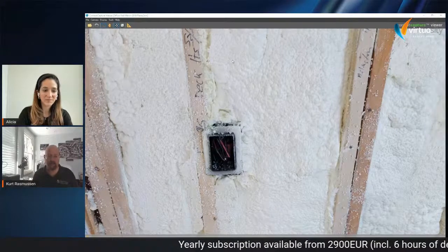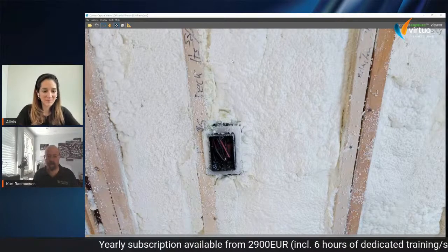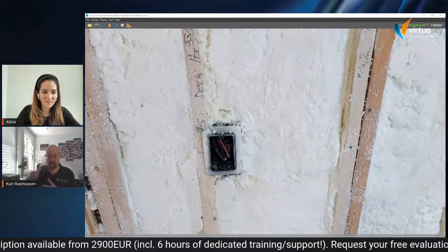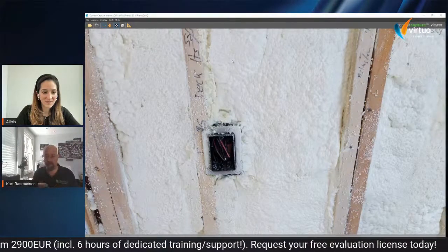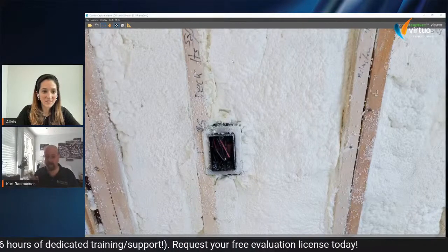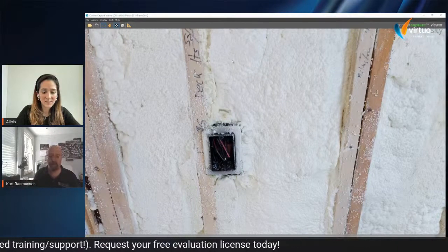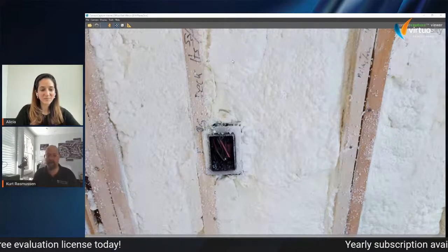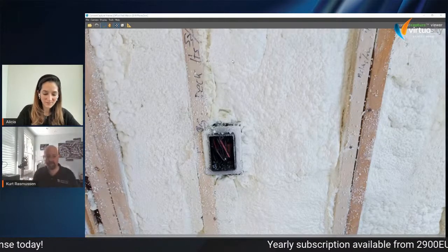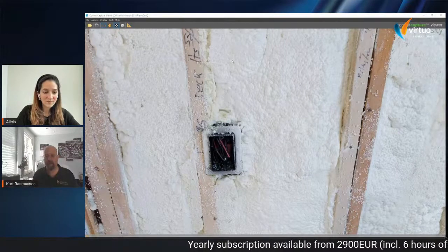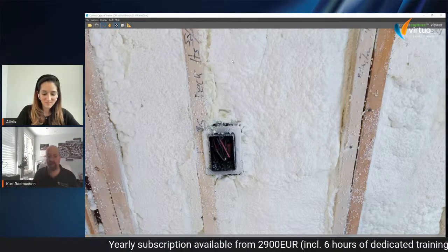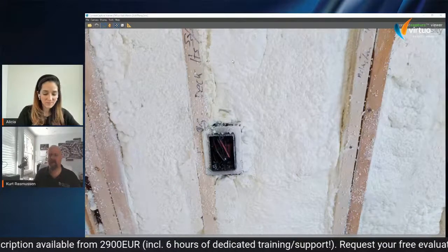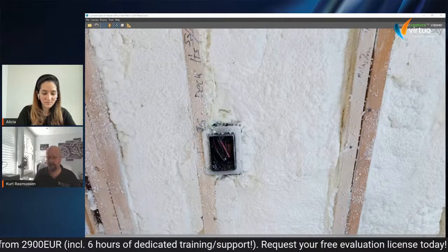And it got to a point where I said, you know what, I can't keep going back and forth with you. And I also have pictures. I bought these small cans of foam, and I went through and did hundreds of spots still before we put the boards up. And then when it comes to the ceiling, I have 6-inch boards for the ceiling, and they're supposed to be 5 inches of insulation. I went through the same process here with the insulation, which was like an R39 or something. Don't quote me on that.